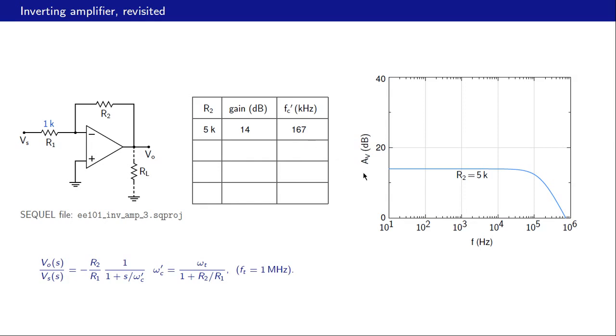And we can see that in this plot here, this is 14 dB. And the intersection of these two asymptotes, this one and this one, should be the corner frequency. So let us see, this is 1 kilohertz, 10 kilohertz, 100 kilohertz, that is 200 kilohertz. So these asymptotes will intersect somewhere between these two, and we see that that is indeed happening.